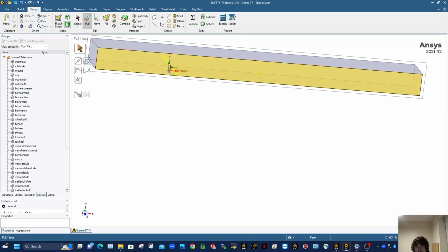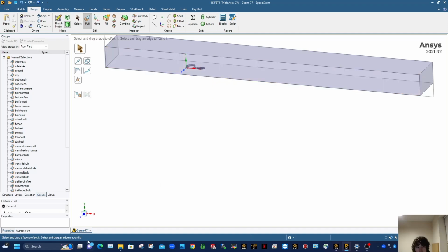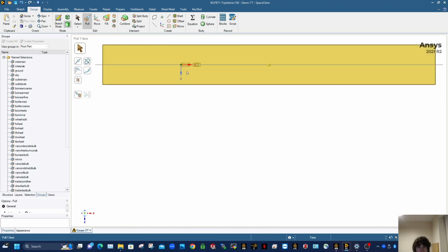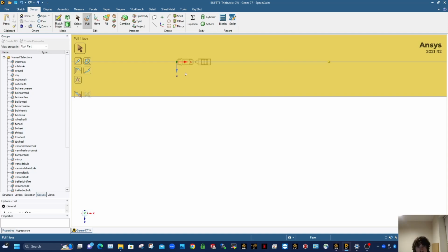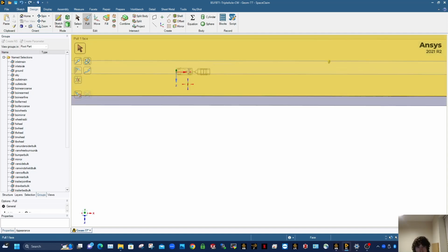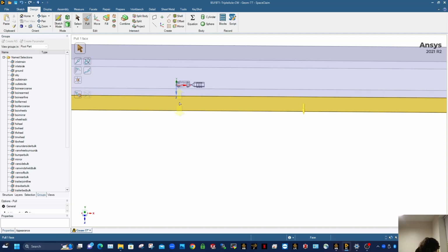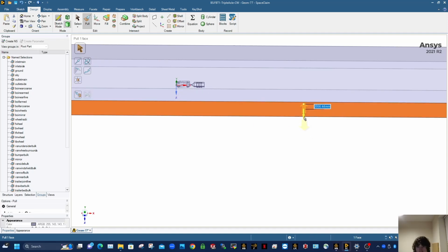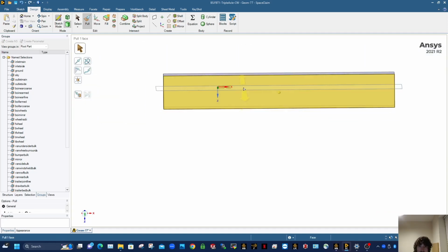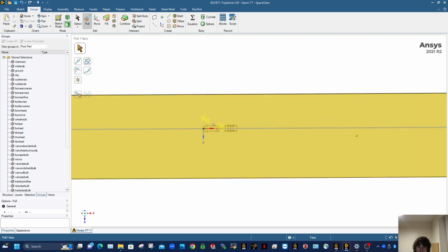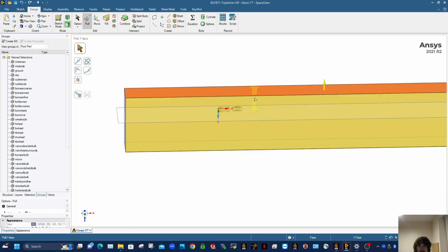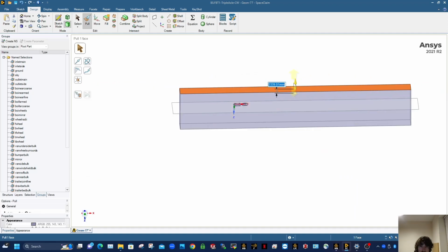The front and back are fine, they're both 4L and 12L. In terms of the width, at the minute it's 4W this way, so I want to add another 2 Ws, W being 2250. I'll grab that, press spacebar and go 2250 times 2. So now that's 6W that way. This here is 4W this way, and that needs to go up to 18W. So pull that, click space. To go from 4 up to 18, we have to add 14 Ws, so 14 times 2250.